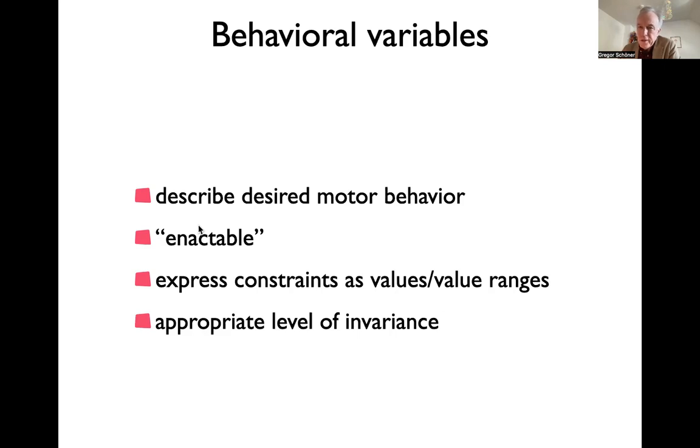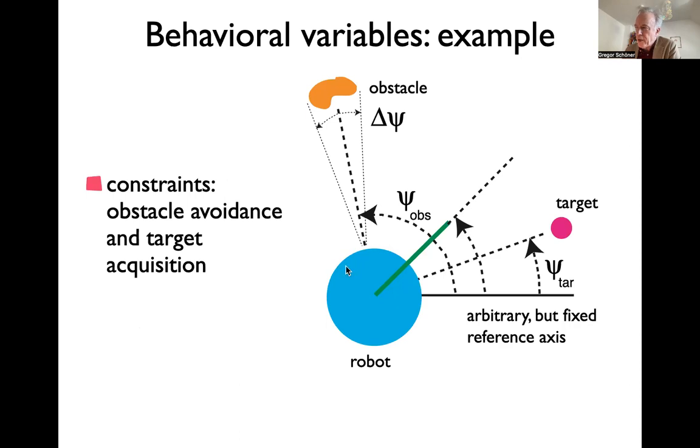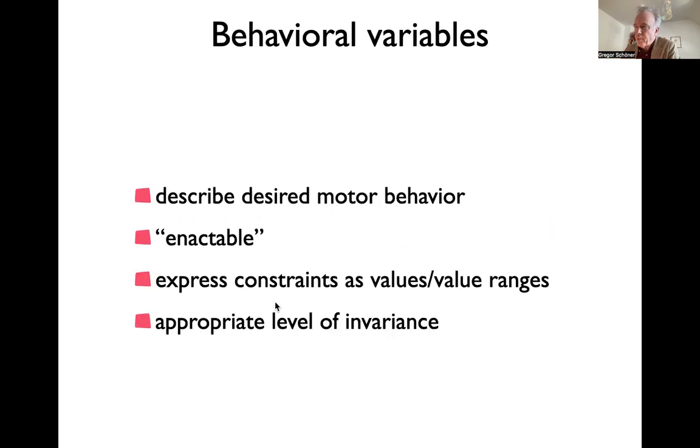And in this robot, as I was hinting, it would be easy to do that, because we would typically assume that there are two active motors, for instance, on the left and on the right, two wheels that you can turn freely. And so by giving these two wheels a joint velocity that moves the vehicle forward, we create constant heading, and by giving them a slightly different speed, we can make the robot move forward and turn. Generally, the mean of the two speeds I give to these two wheels would be the forward velocity, and the difference, correctly scaled with the size of the robot and the size of the wheel, tells you the turning rate. So you're able to create constant values for this variable heading, but you're also able to change it. And in fact, you're able to impose a certain rate of change, a certain angular velocity, onto the heading, and then that will create a trajectory.